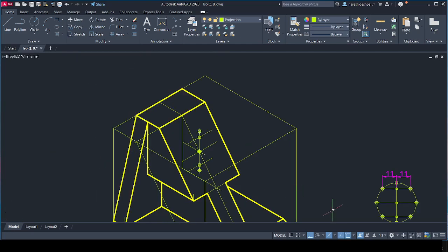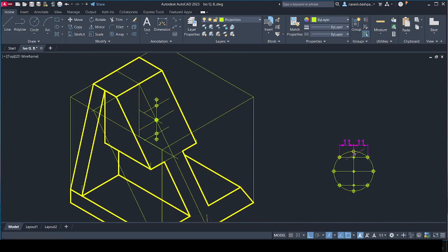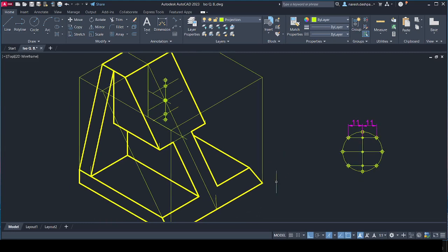Now you see what is being done is simply we have drawn this vertical axis along with these points, and then instead of this horizontal line, now we have the iso plane. This is the iso plane. The front view plane is drawn on this iso plane. So we have drawn lines parallel to this iso axis from these midpoints on the vertical line, and we have transferred these points 1, 2, 3, 4, 5, 6, 7 and 8. I will put up the points here at the end.